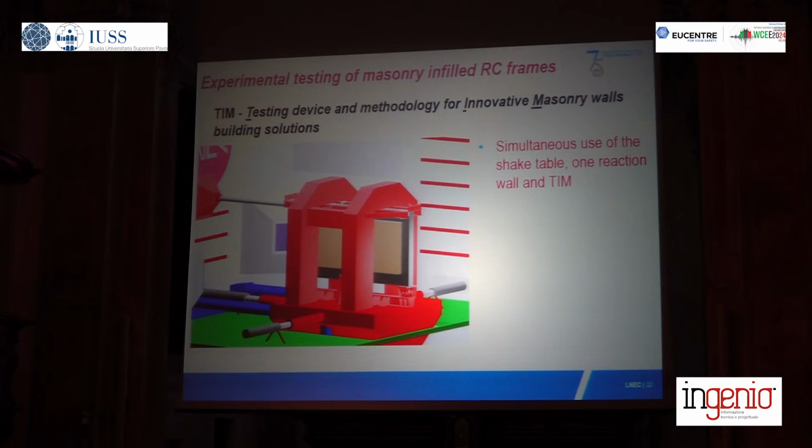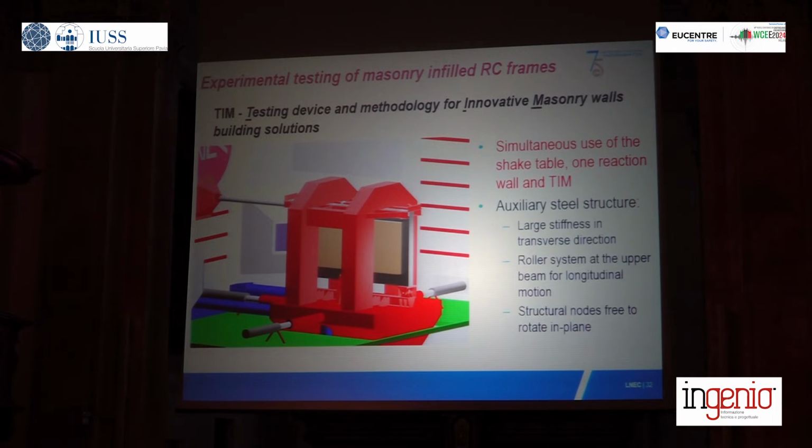So the idea here was to use simultaneously the shake table to impose the in-plane drift and at the same time the out-of-plane action, and one of the reaction walls to actually be able to impose the drift between the two floors of the element. So we have this very large steel structure that you see, the red steel structure, which is very stiff in the transverse direction.